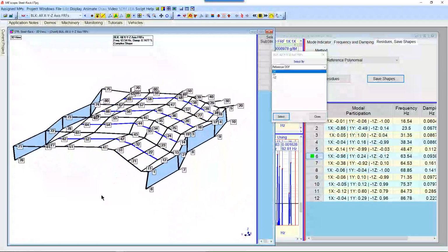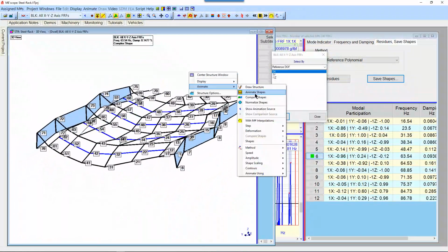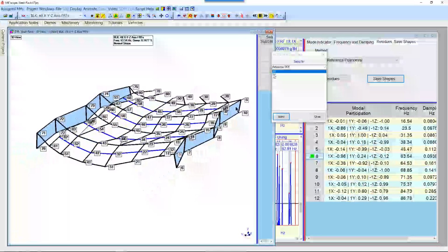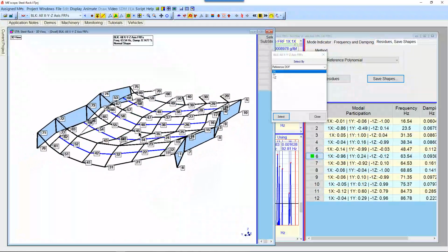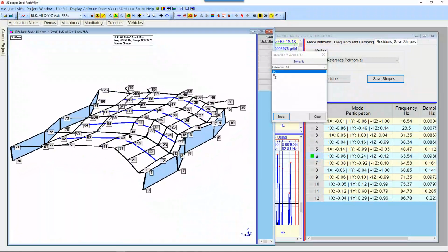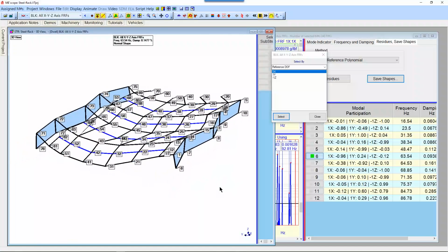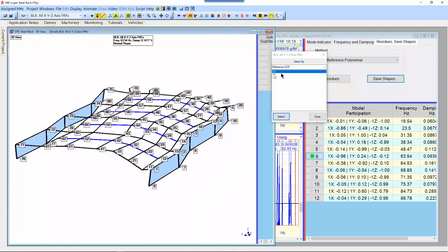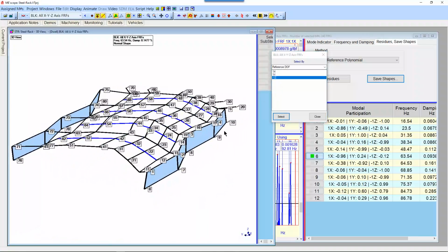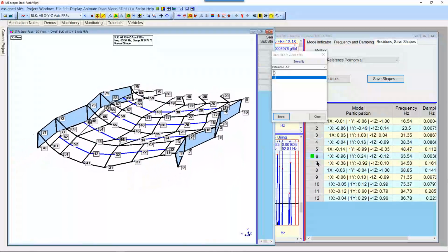You can see that in the mode shape. I could remove some of that by using the Normalize command. Under Animate here, there's a command called Normalize the shapes. That would make it behave as what we call a normal mode, with all the values plus and minus 1 in the mode shape table. Here we're animating right off of the curve fit data, so this is just being converted as it's presented for animation. But again, the curve fitter has given us the same mode shape at each reference. So once I've gone through this multi-reference fitting, let's go to the next mode.